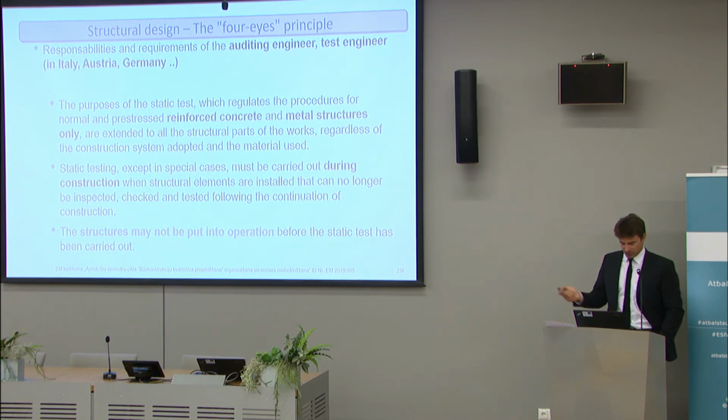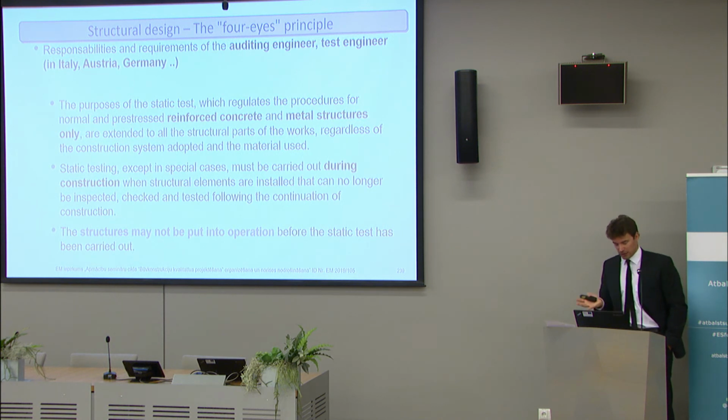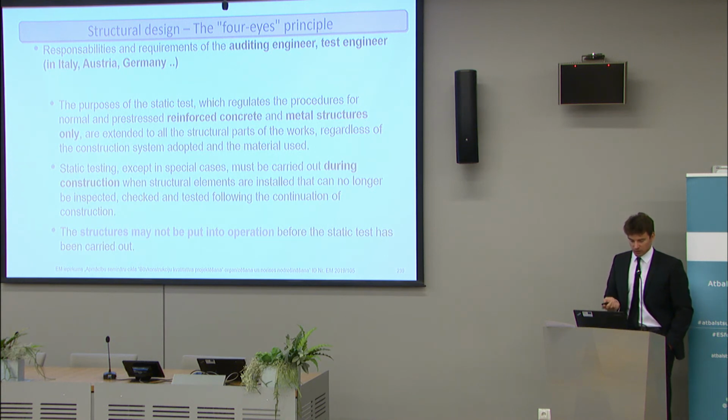Yeah, here it is also said that, at least in Italy, although it's not really well specified, this is related just to reinforced concrete and metal structures, and not to wooden structures. There is a sentence of the court from last year, although, yeah, I don't know. So in some cases, people do it anyway just because they don't want to have problems later. And during construction, this applies when structural elements are installed that can no longer be inspected, checked and tested following the continuation of the construction.